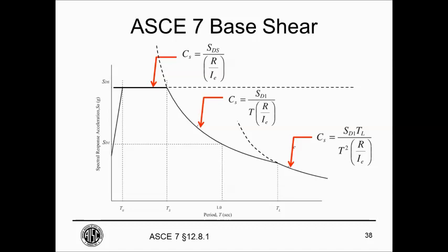If you're in seismic design category, let's say D, you are limited in the seismic systems that you can use, even if wind governs. So you could have a very light structure with very low demand capacity ratios for seismic, but you're still not allowed to use certain systems for the seismic system. And you're also required to follow all the other rules for seismic design that kick in at seismic design category D.